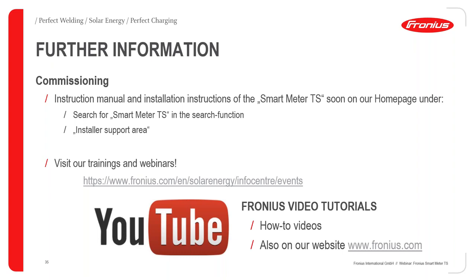I want to point out the 315 milliamp fuses. They were mentioned during the webinar, and there was a hint that they have to be installed. So please let me clarify here. These fuses are regulatory. So in case there are local regulations that need to be fulfilled, you can install these fuses. This is just in case there are some local regulations in your country. So please make sure to comply with these local regulations. If this is the case, then please install these fuses with 315 milliamps.